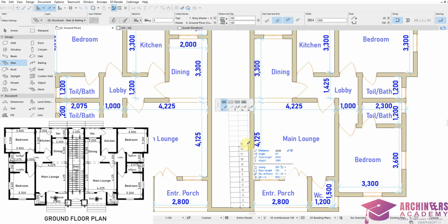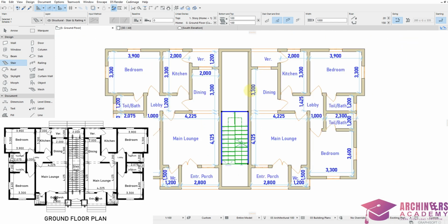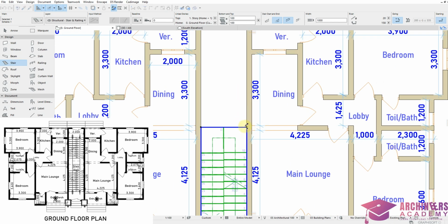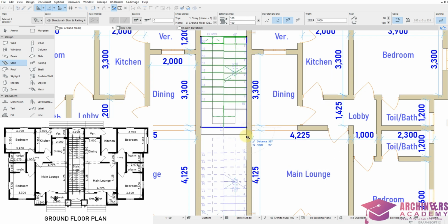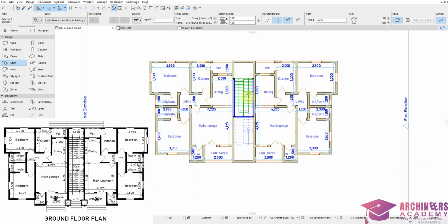Make sure that it is straight. 4, 2. We can adjust this back and maybe 1, 8, and offset back. Then you can also use mirror again, Ctrl Shift M, to mirror this. Then we'll lap this on this existing one. We'll do a lapping. So by so doing, we have placed our staircase. So this is how it's done.